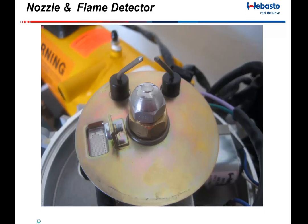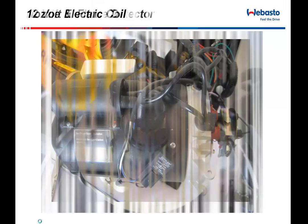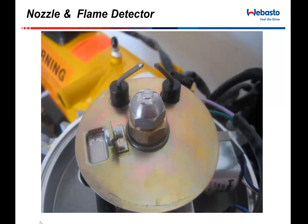Over the top of that nozzle is a 12 volt coil. It's a 6,000 volt coil. If you guys mess around with it in the shop, it'll pick you up and throw you right across the room with no problem. But when I'm first turning that unit on, for 20 seconds that fan motor is spinning. Basically what it's doing is priming fuel to come to it. Fuel comes up, comes through that nozzle. We make a spark with our electrodes and we create a flame.